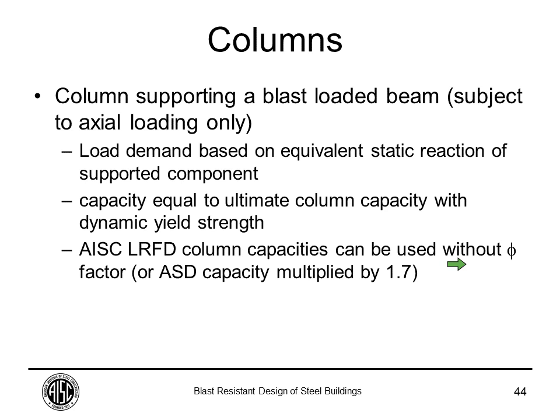I know that ASD and LRFD are being combined, but we left this note here because we see this all the time: when you specify an equivalent static load based on the dynamic moment capacity of a blast-resistant member, those loads should be treated as a factored load. So you want to make sure that you at least are comparing that to LRFD capacities. We have some structural engineers that still use the ASD approach, where, if you're not looking at the load side of the equation and you're just looking at the capacity side, the ASD capacity can be less. So generally, if you're going to be comparing an ASD capacity to an equivalent static load, you get to increase it by about 1.5 or 1.7.